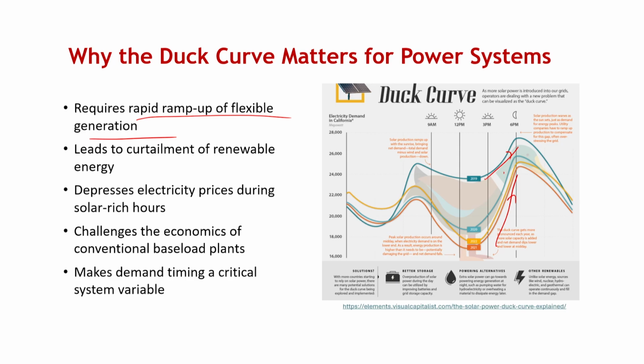It may also lead to a situation where you may need to cut the renewable energy generation, because you may not be able to design a system which can give you this kind of peak power and goes as low as this to give you the power when you have the solar at a maximum. Maybe the system will get tripped if you go beyond this point. So you may have to generate this much power throughout the day. At least the minimum energy that you need to generate is this much.